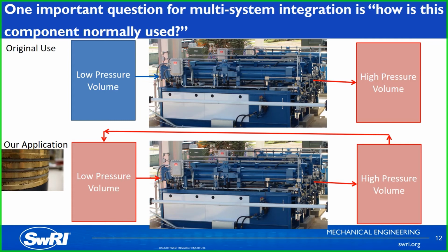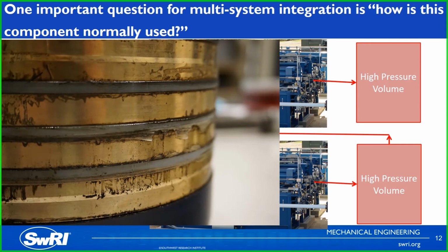So even though the compressor was built to handle the temperature at the end of the compression stroke, it was not built to handle the pressure or the temperature at the inlet going through the entire stroke. And so what that did is basically melted the seals on the compressors themselves, and so we were getting a lot of leakage, and we couldn't meet the flow rate we originally had.